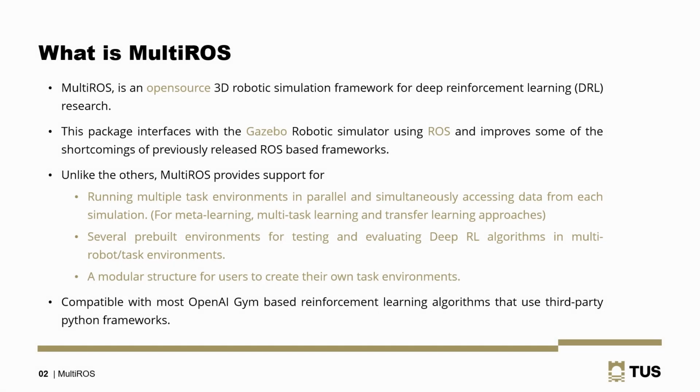We present MultiROS, an open-source 3D robotic simulation framework for deep reinforcement learning research. This package interacts with the Gazebo robotic simulator using ROS and provides a modular structure to create ROS-based RL environments. Unlike the others, MultiROS provides support for training with multiple environments in parallel and simultaneously accessing data from each simulation.